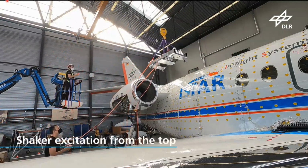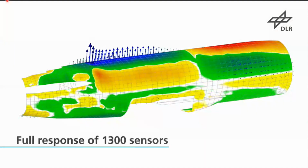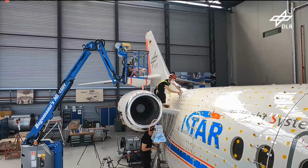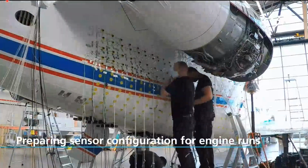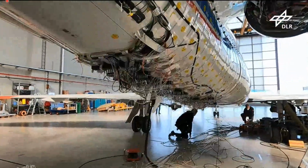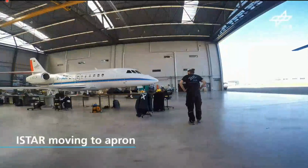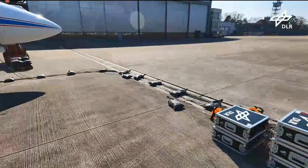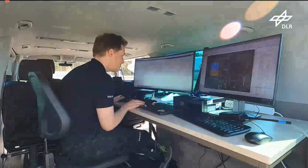This is the excitation on the top of the aircraft. And here you can see the full results for the full fuselage. After configurations 1 to 5, we pushed the sensors back to the tail of the plane in order to prepare for the engine runs, and we had to tape everything down, all cables and also the patch panels, so that the aircraft could roll out onto the apron where the engine tests were performed. We set up our measurement equipment there, and then the engines were turned on.